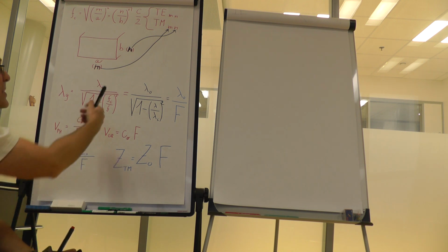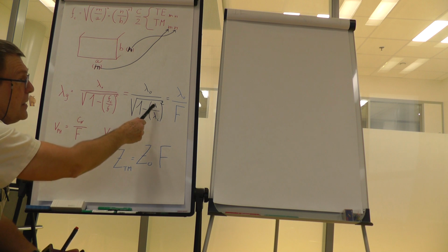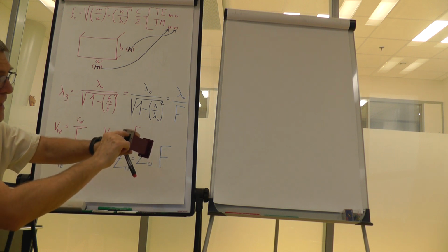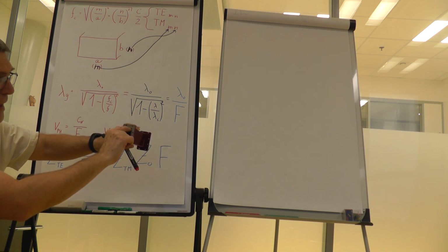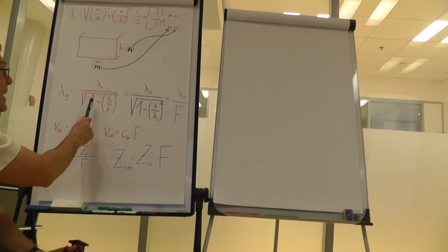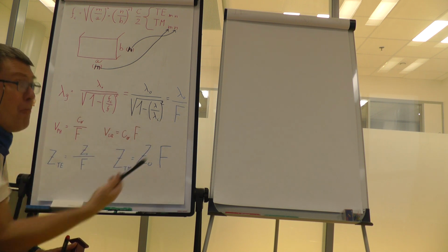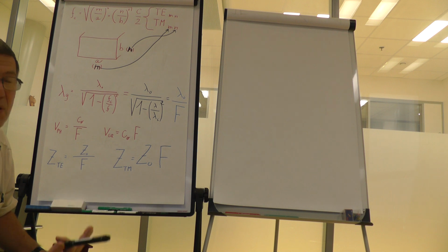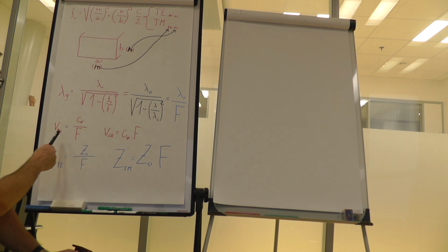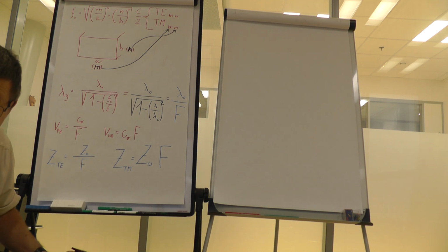Well, of course, this ratio could be replaced by the current free space wavelength of the propagating wave divided by the critical wavelength, which is 2 times this distance for the TE10 mode. Or, to make things simpler, we can in this formulation call f a factor that prolongs the wavelength, for example, but it also is present in other expressions, like if we try to calculate the phase propagation speed,